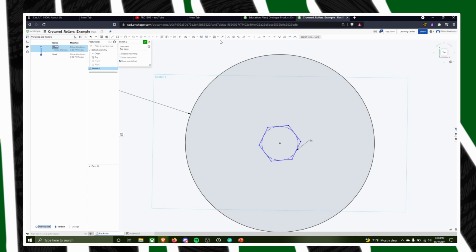And then similarly, it's 1/2 inch hex, which is 1/2 inch diameter hex. Grab this and we do the dimension again. Click on the circle that the polygon is inscribed in, and we want it to be 0.5 inches or 1/2 inch.